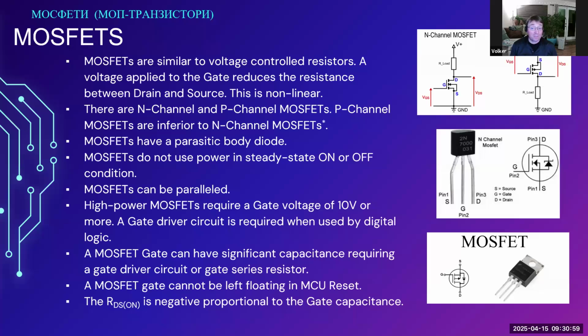One effect of this is switching power supplies. If you're looking at integrated circuits for switching power supplies, for the vast majority, like 95%, you can right away tell that they're using an N-channel MOSFET as the internal switching element because they use a bootstrap capacitor. I will talk about that later, if given the time. The same thing with MOSFET gate drivers.